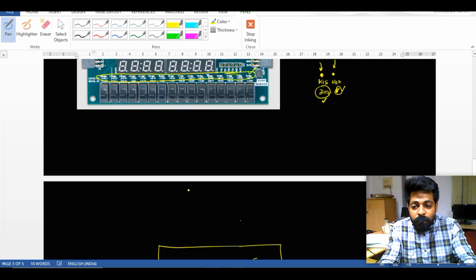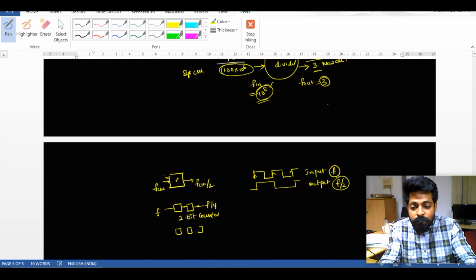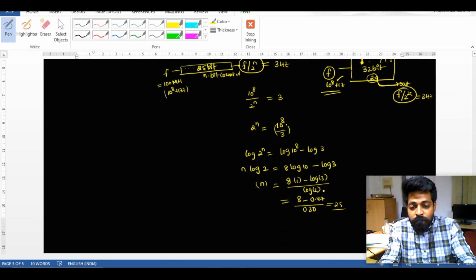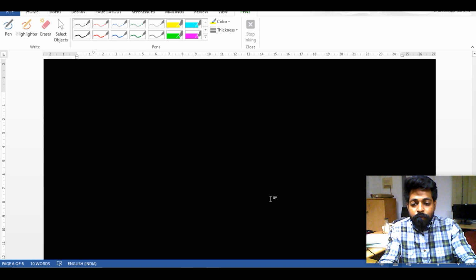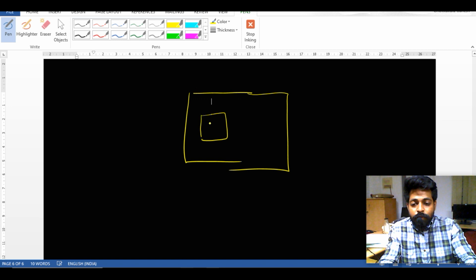So the implementation of that entire combined circuit should be over here in the FPGA. Yes. So my new combined circuit should be like this. First of all, I will be designing a clock divider circuit, and there I will be combining it with the counter. What this clock divider will do is take a system clock from the E3 pin, which will be the frequency of 10 to the power of 8. So this is called a direct clock.